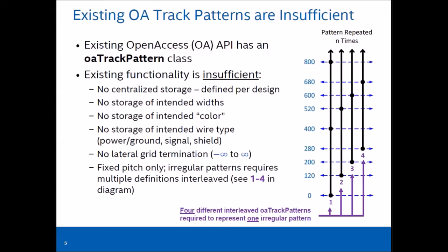It's not really centralized. There's not a place to store this in a central place within OpenAccess. You can define it, of course, with the API, but it's up to the application on how to centrally store that outside of OpenAccess. There's no concept of multi-patterning. Actually, I don't think it exists anywhere in OpenAccess, and it doesn't exist here either.